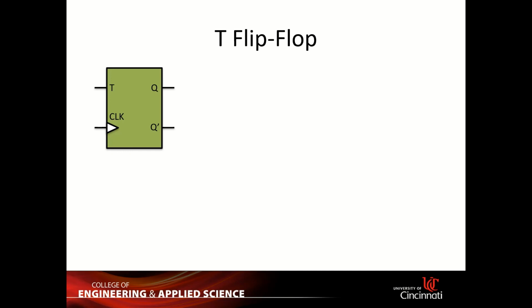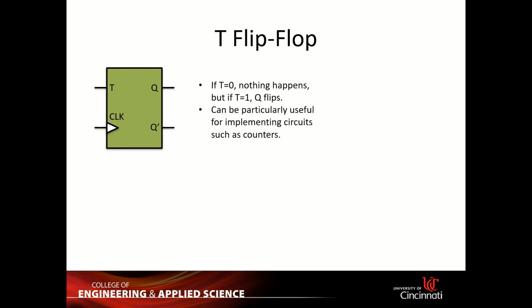Sometimes you don't need that many things to work with. Maybe you only need that hold or flip function. So you don't care about hardwiring your output to some number, or giving the output a 0 or 1. I always want to either flip or hold the value of Q. So what do I do? Okay, I make a T flip-flop. I will explain why.